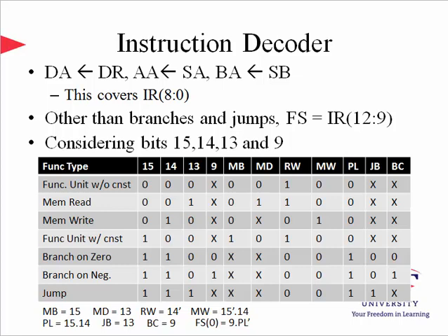However, the 9th bit is also the last bit of the function select, FS0. In order not to contradict with FS functionality, we need to differentiate FS0 from BC, which is equal to the 9th bit of the instruction. It can be observed that if we AND PL prime with the 9th bit, we essentially focus on the functional unit where we use FS bits actively.